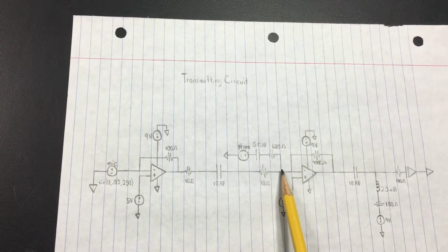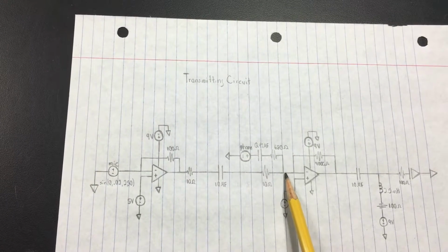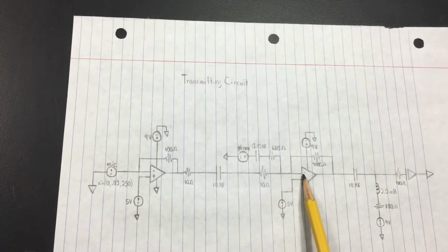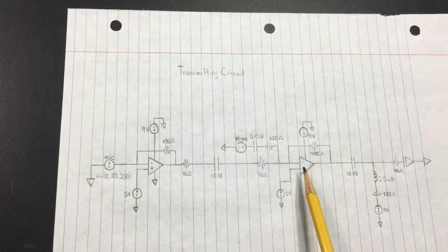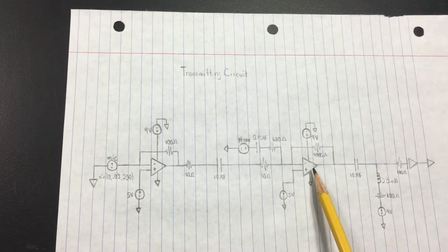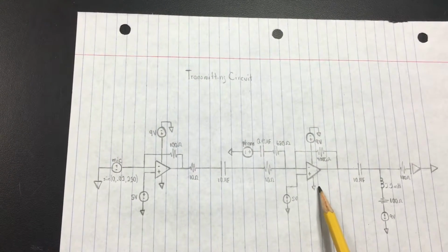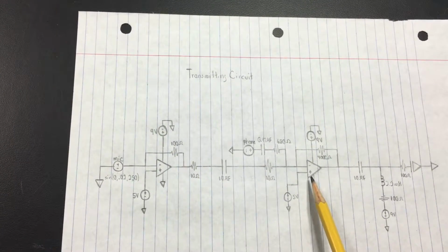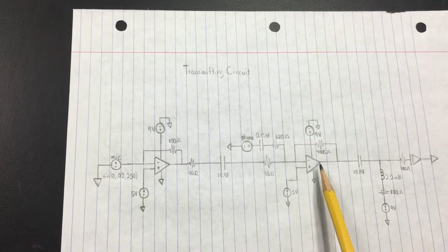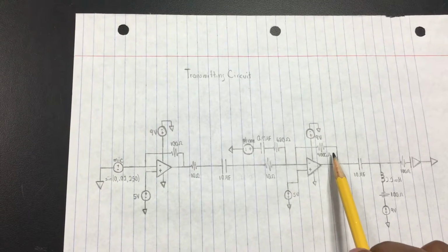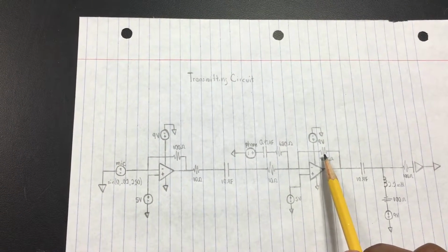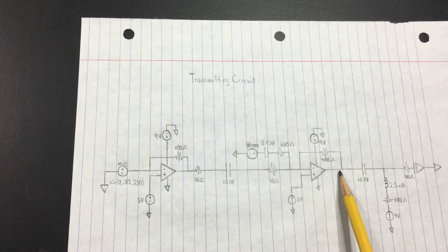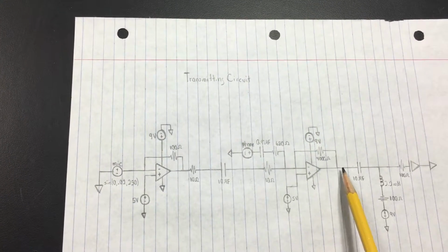And now those two signals from the phone and the microphone are both mixed and sent into this second operational amplifier. This op-amp is also powered by 9 volts and grounded on one end, and we also see 5 volts coming into the positive end through another voltage divider. This output is then amplified even more through a 4,000 ohm resistor, and we see an even greater gain.